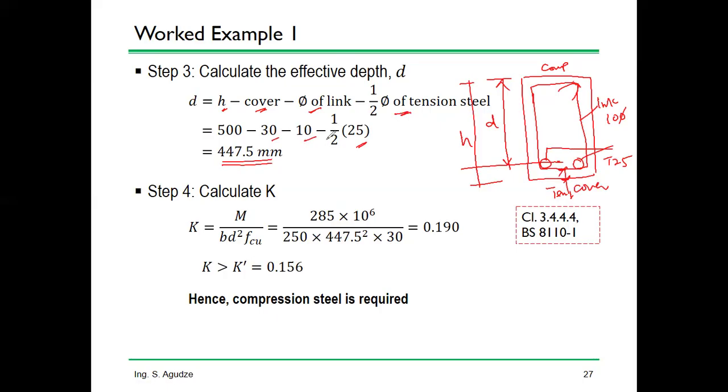It's very important to calculate your effective depth well. Okay? So what I will tell you is that in calculating the effective depth, usually you would have to assume a diameter of your main bar so that you'll be able to use it for that calculation. So typically after the calculation, you may want to cross-check again whether the effective depth you use is fine.